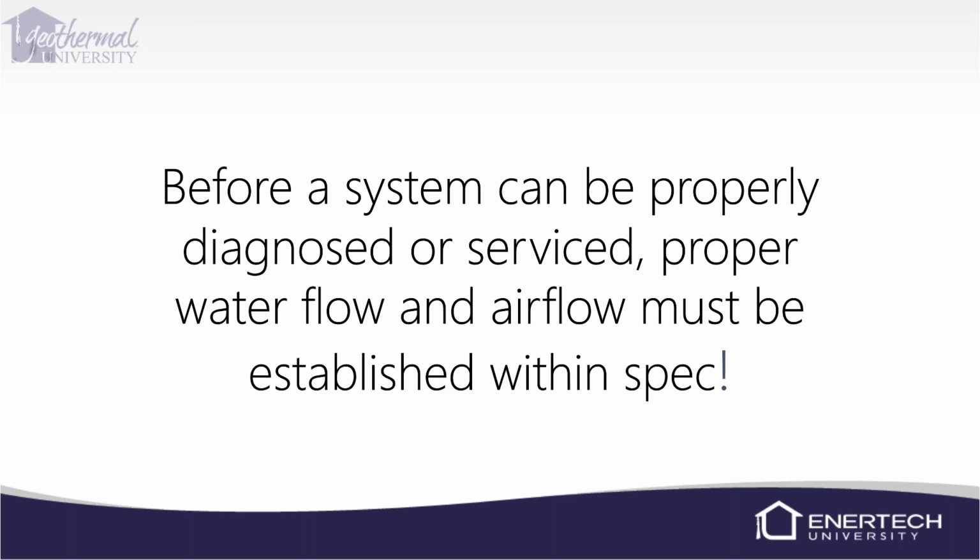The water flow, we're going to have to take pressure drop. Now, if you have an older flow center, maybe like a QT flow center from B&D, you will have to use a flow meter tool because pressure drop is not accurate. The newer NPE flow centers from GeoFlow are pretty good with pressure drop, so you should be okay there. But some of the older ones, you will have to have a flow meter tool.